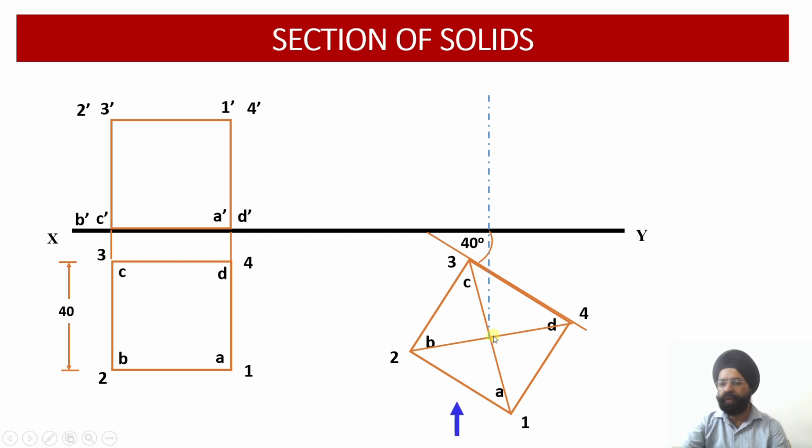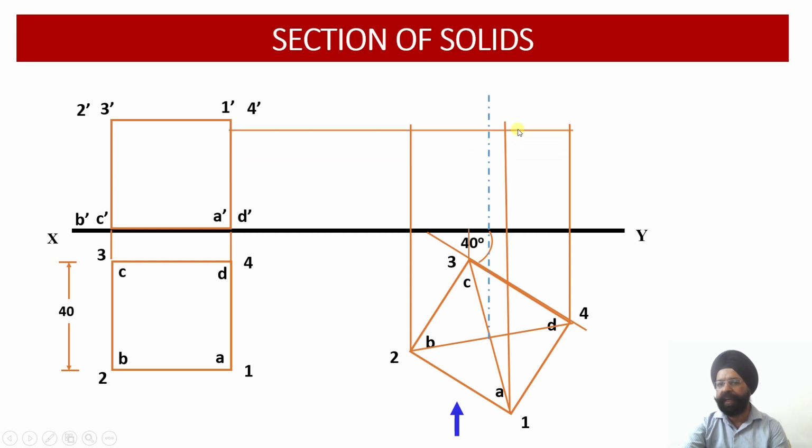So having worked out the axis point, now we need to draw the front view as well. So we have drawn projectors through all these points. So axis height will again be 40 millimeter. So we can draw this projector over there. So we will be getting 40 millimeter height straight away, right? So once again, let us mark these points. On the bottom, it will be A dash, B dash, C dash, D dash. Similarly, 1 dash, 2 dash, 3 dash, 4 dash will be there at the top.